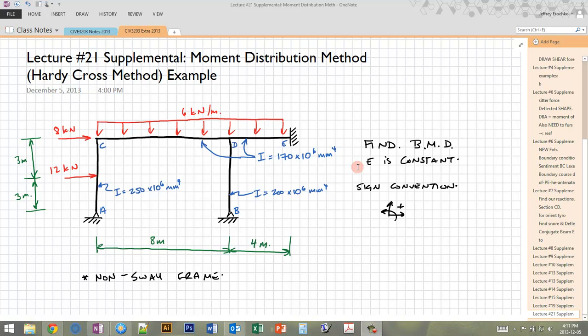So if you recall, for the force method, we always have to solve a simultaneous set of equations that's equal to the degree of indeterminacy of that structure. And for the slope deflection method, we always have to solve a system of simultaneous equations that has as many equations and unknowns as the number of free degrees of freedom of that structure. For the moment distribution method, it takes a different approach by solving the entire structure step by step in a continuously improving approximation that actually ends up with an exact result.